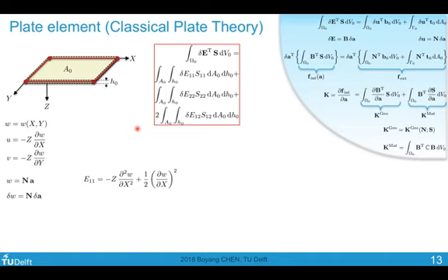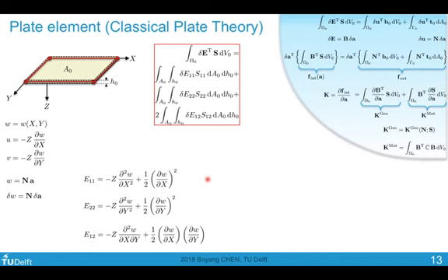And next we follow the same drill. We calculate the Green-Lagrange strain. There is a linear term and a nonlinear term, and we repeat the same procedure for the other strain terms. And then we calculate their variation with the objective of sorting out the B matrix. Eventually this would give us the B matrix, and this is with respect to the axial strain in the x direction.